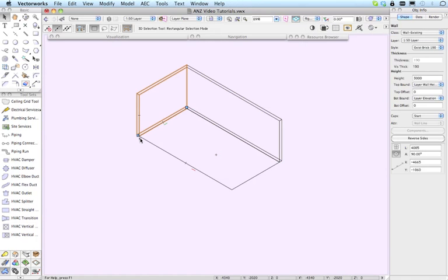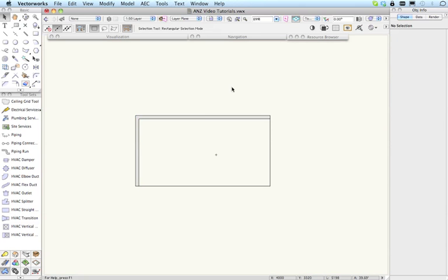Here are my two walls and something that might represent a little piece of floor. And I want to go ahead and put a few little electrical symbols in here. Now, with all of these symbols, I would recommend that you have a class that you nominate for these things to go into, because that's going to make it much easier when you want to show the electrical services plan on top of, say, your base plan, and it makes it a bit easier to do a few other things, which you'll see.